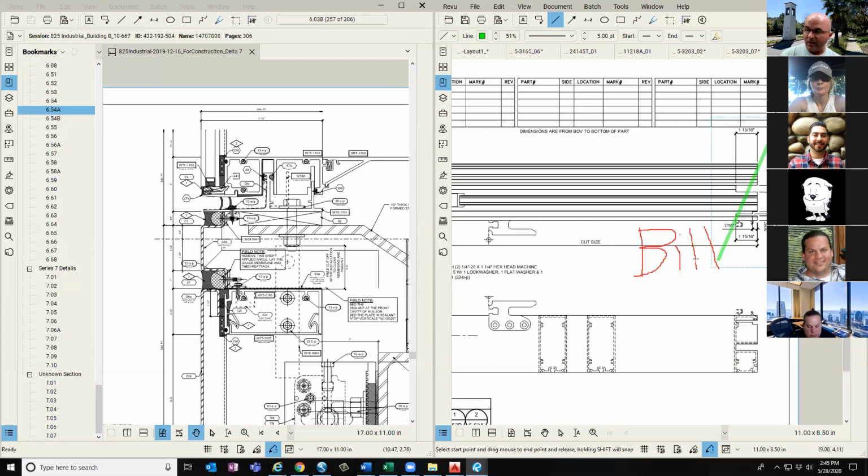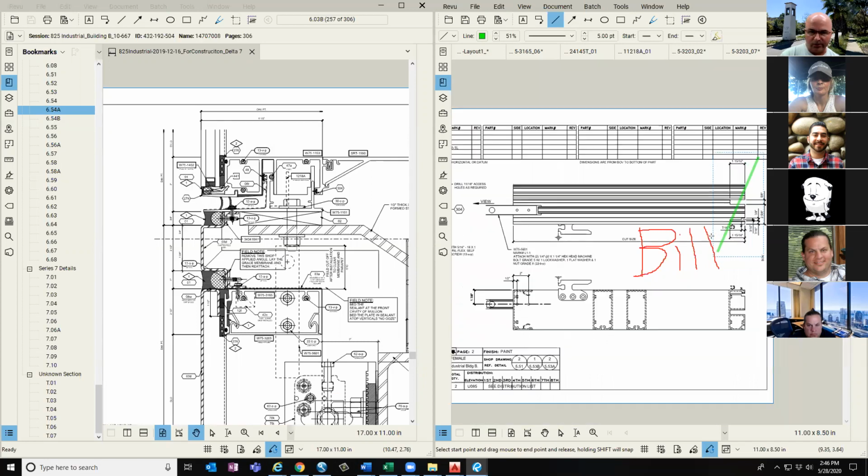However, if these have been vetted through prototype units and it's a typical condition, this notch should be pretty standard, and I shouldn't have to measure every single portion of this dimension. If I've had this handoff meeting, which is part of that checklist meeting from the very beginning, and we verified that this has already been approved as the correct size of the notch. If this hasn't been approved by the time I get to it, I'm going to verify every single dimension to make sure that this is the real wind load notch that I want to use here.